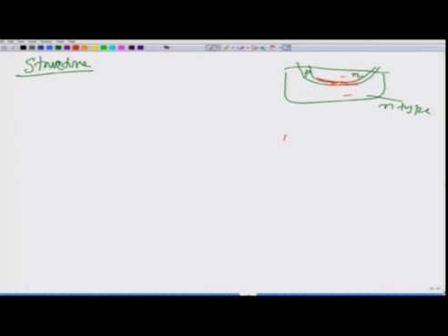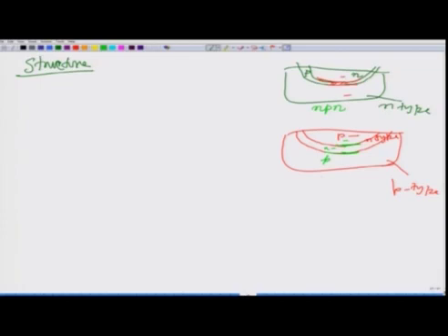Or you can have the reverse of it. You can take this basic wafer, which may be p type to start with, and then you diffuse on this some n type, and on that you again diffuse something which is p type. So, this is also a possibility. You have a p-n junction here, and another junction here. So, you have two types of possibilities. This type is known as NPN transistor, and this type is known as PNP transistor. NPN means you have P sandwiched between n type and n type, and PNP means you have n sandwiched between p and p.